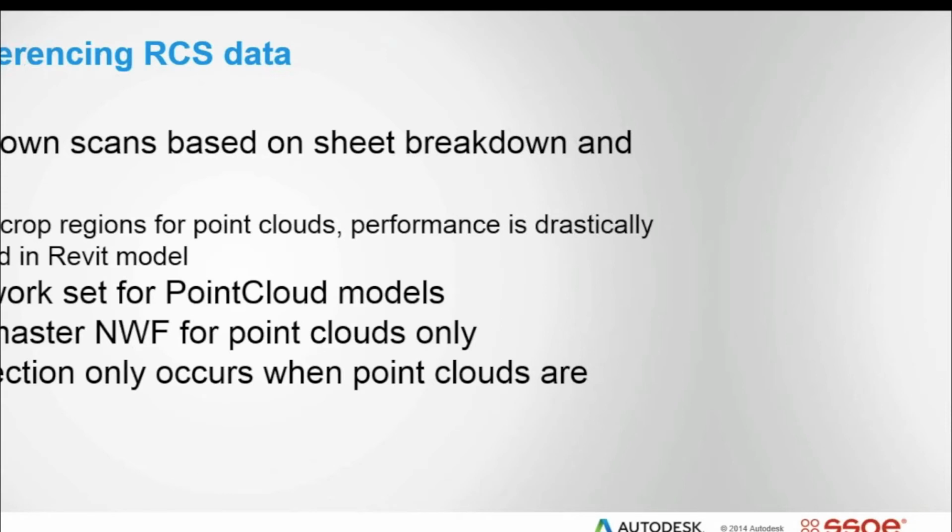Also, create an NWF, so in Navisworks, make your master NWF for point clouds only. So when you have your Revit models or any of your other design models, you can bring that NWF in as an attachment. It brings everything else in there. And clash detection, this is a note we've recently come across: clash detection only occurs when the point clouds are visible, so put that in the notes. If you have your point cloud hidden when you run clash detection, it'll show 0 clashes. So either you have the best design project of all time where you didn't hit anything existing, or the point clouds were hidden, and that's what happened for us.